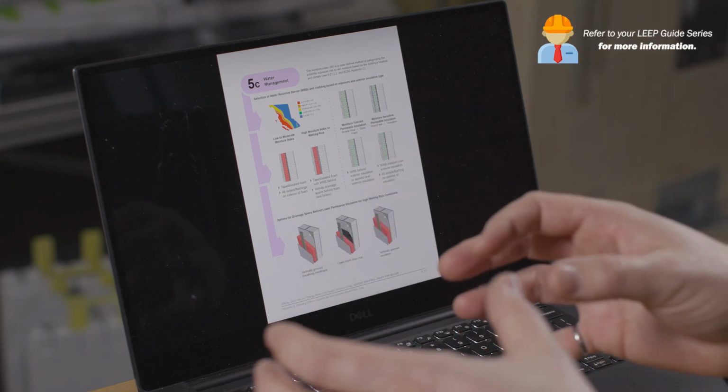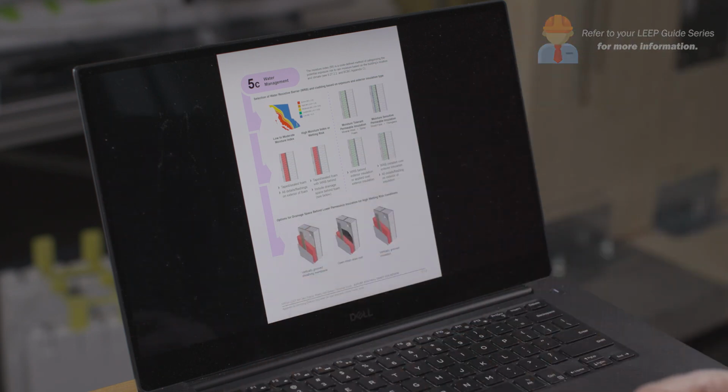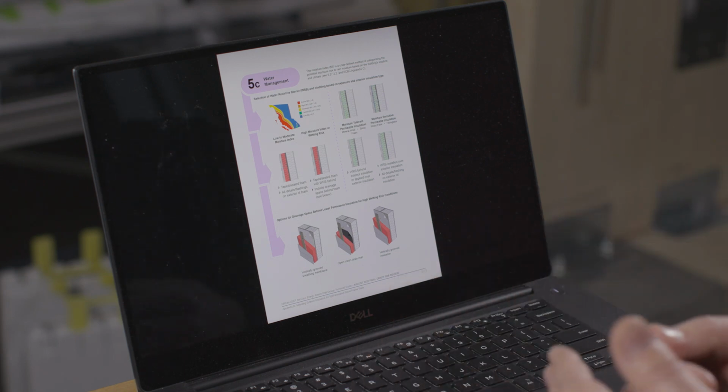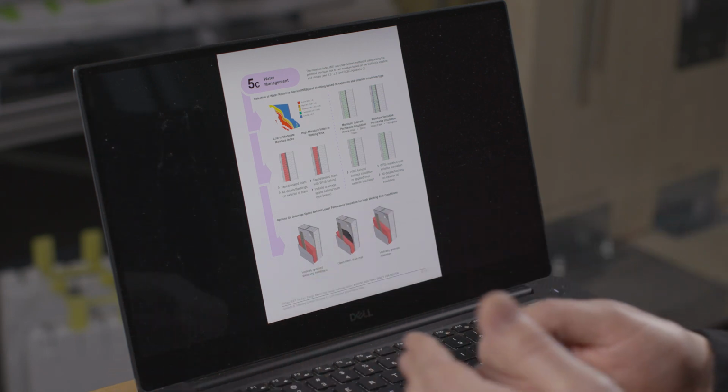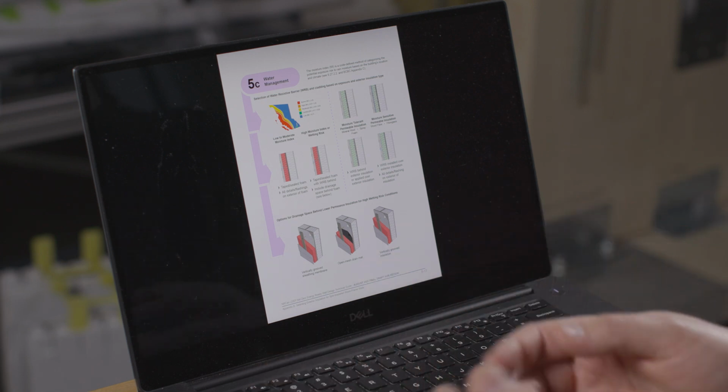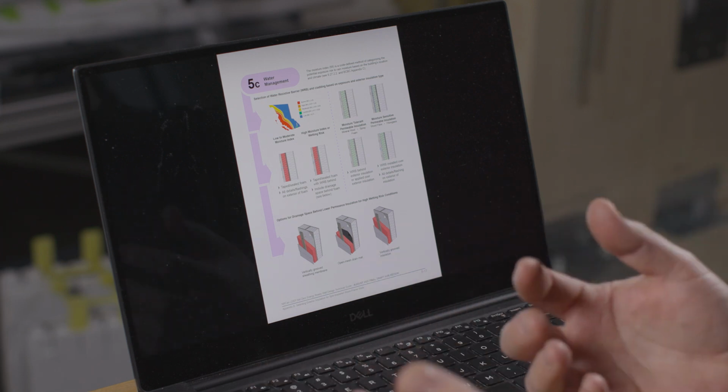The third thing that gets looked at is water management. So you've got your assembly, you've got the exterior insulation, some thickness of exterior insulation. Then what do I do for water control? What's the best thing I could do? And what's going to drive this is where you are. Are you in a wet region of the country? Are you in an area with a high moisture index?